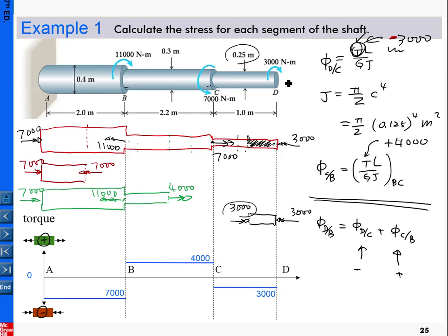You should be able to determine the direction of the relative angle. If you have a small guy sitting here looking into the shaft, the twist angle from this small guy's viewpoint could go one way, or it could go the other way, and that can be told by the sign here. For example, if the whole thing comes out negative, then you go to this viewpoint. When applying the right hand rule from this viewpoint, that should be the circulation in this way. Good.